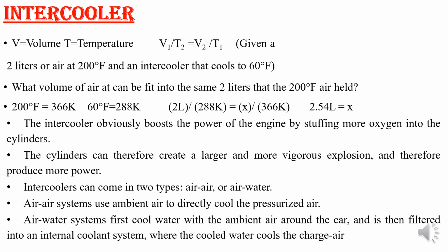That time is known as spooling time. Once the spooling time is achieved, only then will the turbine work, transfer power to the compressor, and the compressor will compress your air. So turbo lag is considered a negative characteristic in automobiles.